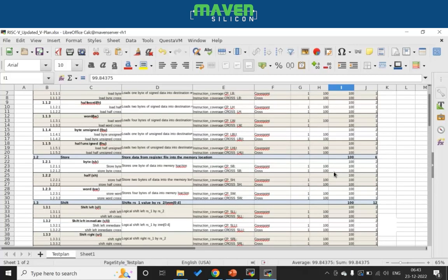All right, so this is how we have verified the RISC-V core design and made sure that all the instructions are working fine. And as part of the next implementation, we have even written a few more test cases to verify the execution of assembly programs also, so that instead of each single instruction, a set of instructions executed in a sequential manner is verified, and we have implemented a few test cases for verifying assembly programs as well.